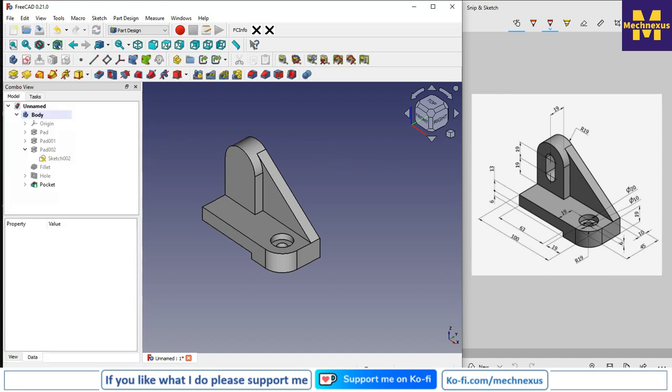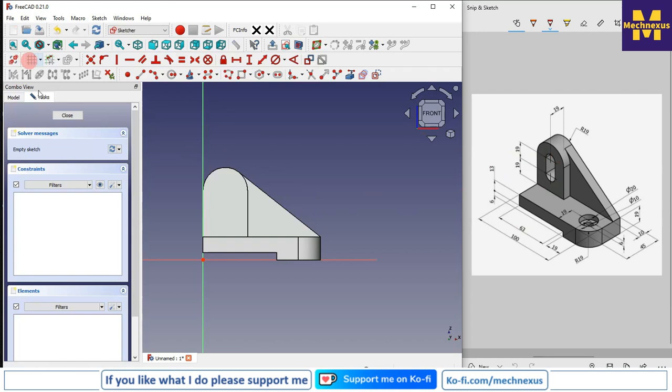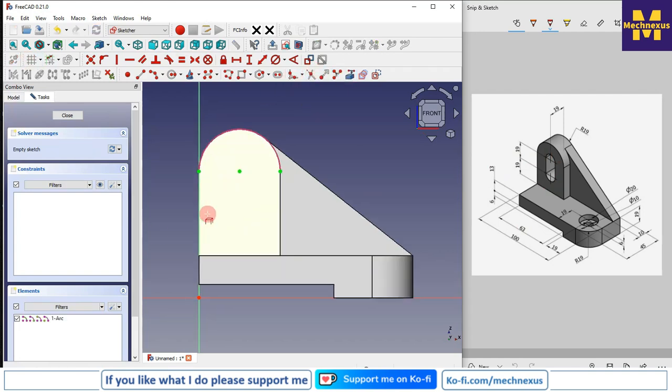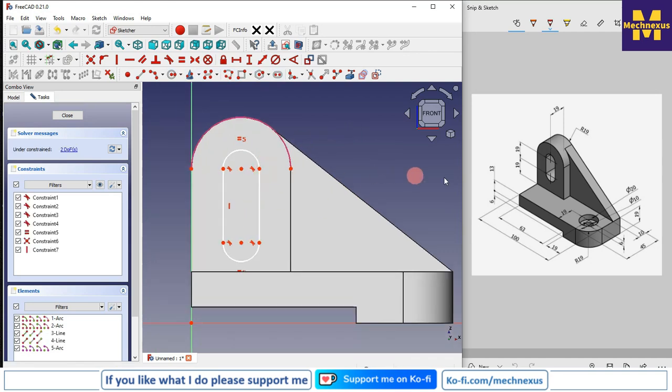Now we will create our slot sketch, which is this slot. So we will select the face and click on the sketch. We will click on the project geometry and project this outer arc, and we will go to the slot tool and center to center is of 19 mm.